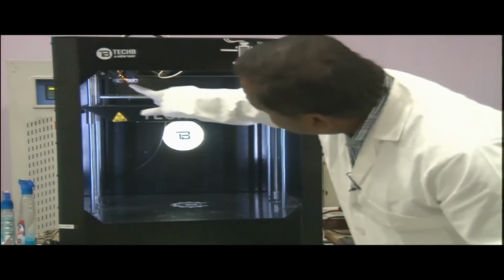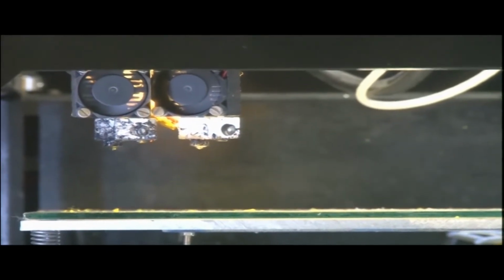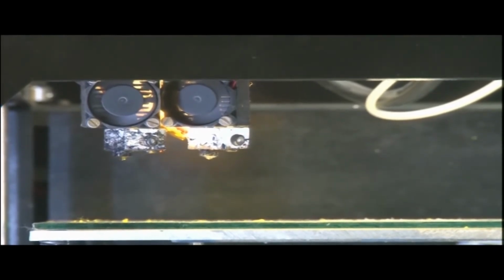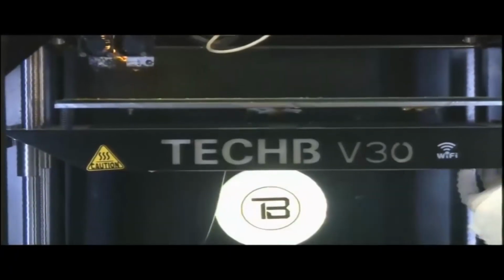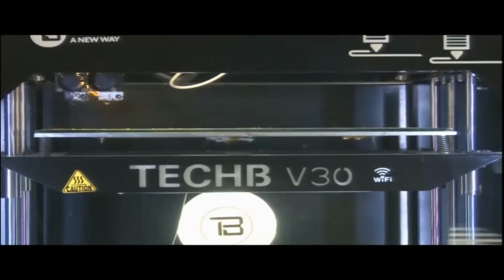For cooling, we have to check that the two fans just above the head are running. We also have to take care of the flatness of the bed, and we can adjust the level of the bed with 4 screws. You can see screw 1, 2, 3 and 4. These 4 screws are loaded using a spring mechanism.